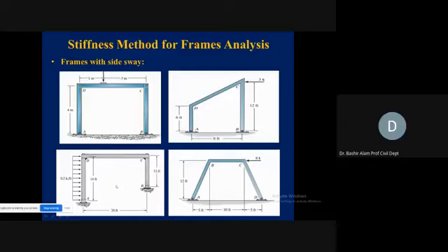Now the bottom left one, AB, again we have hinge supports. But if we look at AD, we have a lateral load of 0.2 kip per foot. At the DC level, we don't have any constraint in the horizontal direction. So it is going to go sidewise. And again, the left vertical member, AD, is not similar to the BC member, the right member, which is 12 feet. So again, clearly just by observation, you can see it is a side sway frame.